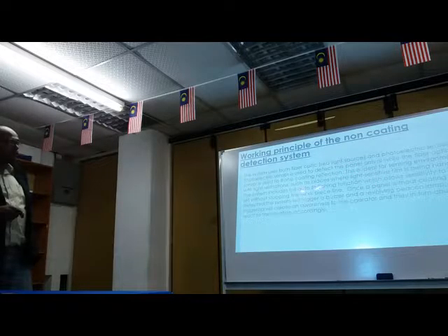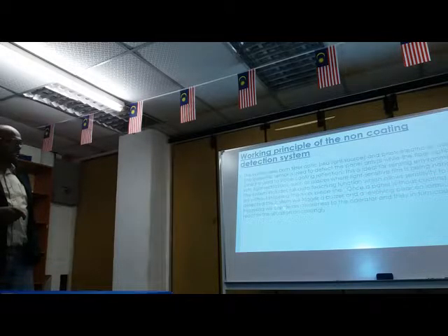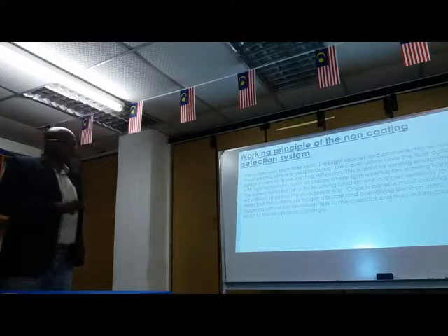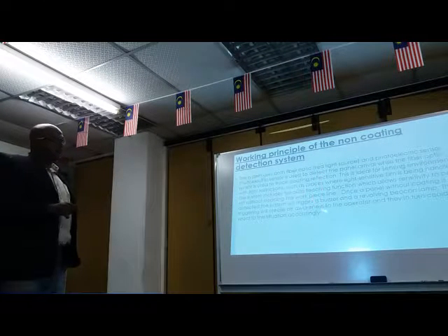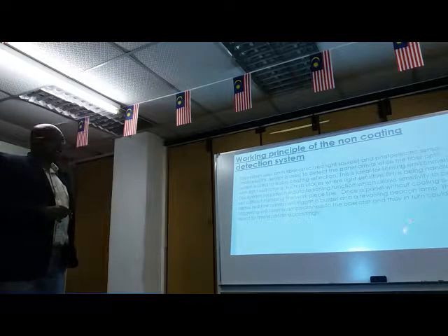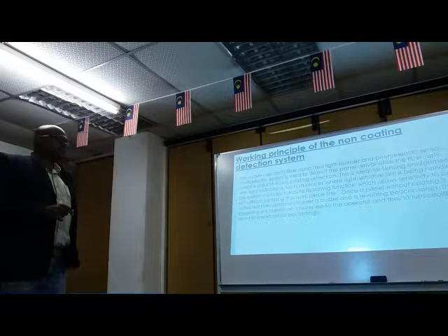The system includes a full auto-teaching function, which allows sensitivity to be set without stopping the work. Once a panel without coating is detected, the system will trigger a buzzer and a revolving beacon lamp. This triggering will create awareness for the operator, and they in turn can react to the situation accordingly. This is what we want. We don't want any panel to reach the final processing area or even reach the customer.